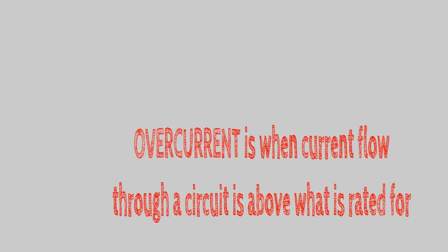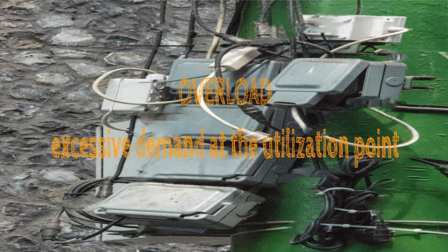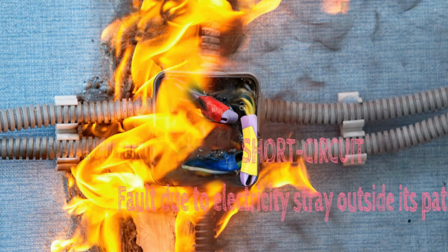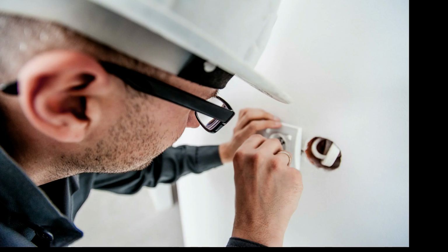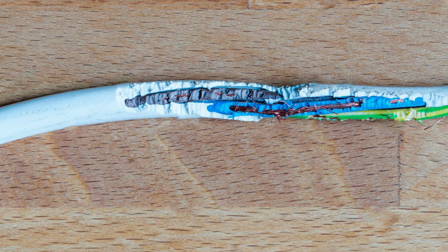Overcurrent is when the current flow through a circuit is above what is rated for. It can be an overload, which means excessive demand from the utilization point, or a short circuit, which are faults due to electricity stray outside its pathway. This may be as a result of faulty insulation, loose connection, or faulty wiring from the appliance's end, making hot wires touch the neutral or the grounded system.